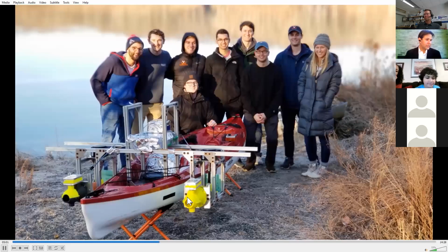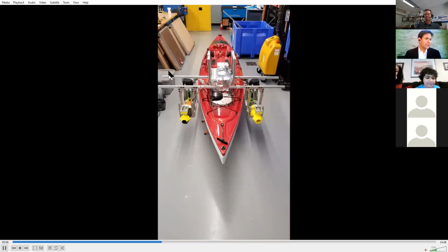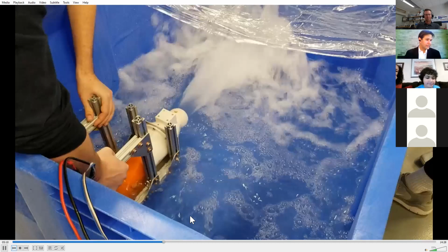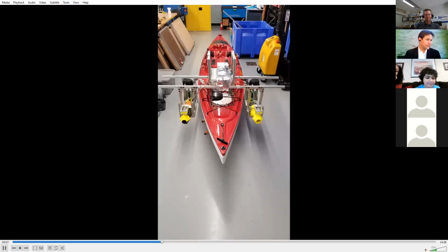This is another senior project where we built water jets into a kayak. So we thought it'd be kind of cool to have a jet ski kayak essentially. And this was testing it. They worked out the computational fluid dynamics for this, so they actually optimized these 3D printed impellers inside of each of these engines. They're running off of big, I think 150 watt brushless motors that are meant for scooters. And again, all this is controlled off a Propeller 1 chip. And it also has these DC motors, quadrature encoders that are controlling the jets. So they can actually steer differentially by aiming these nozzles as it goes.